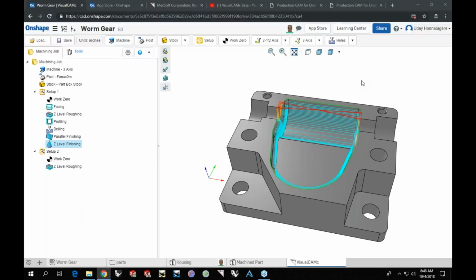The cutting tools. You can switch your library. Owen was asking about metric and English. Are the libraries unit specific? They are. You would have one library for tools in English units, which is inch, and one for millimeter units, so you can have two separate libraries.